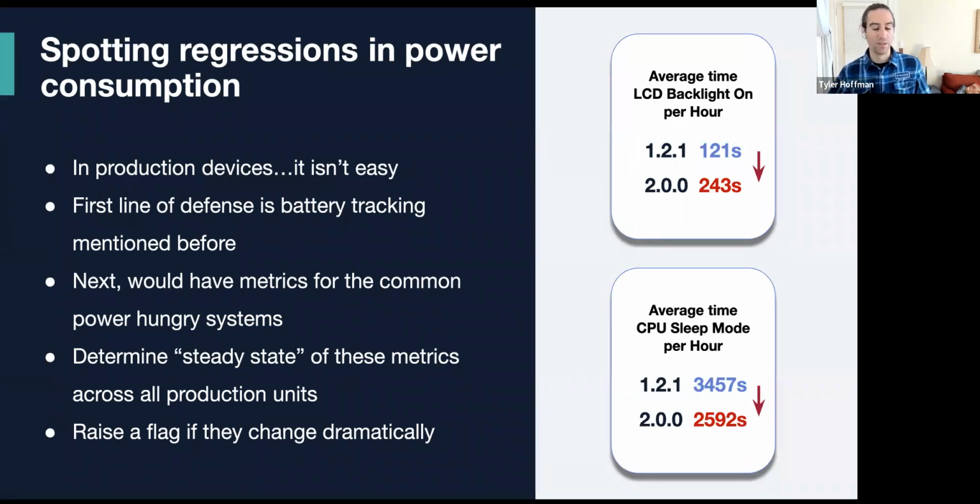We got 7 days of battery life, and then we were ready for the next version internally. So we caught a 2.1, and then we ran that internally for 100 employees at Pebble for a day. And a lot of people would complain about battery life. Almost every single battery life issue was around the accelerometer being stuck on, the Bluetooth chip not being able to connect successfully and so always scanning, or the CPU having a sleep mode bug.